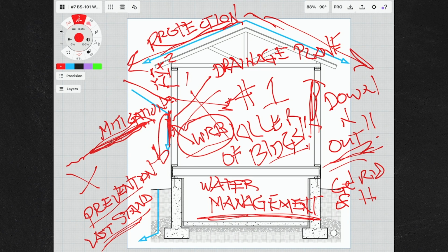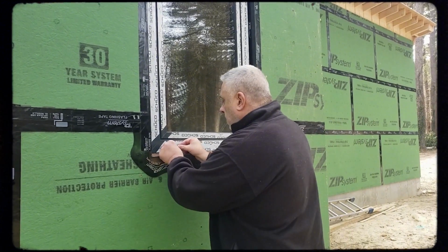Yep. Right. And most of the time, the good window companies are taking care of that. They're not selling you a leaky window, right? They're providing you that protection. But all of the good window manufacturers also have mitigative solutions in their windows, their components. If water gets in, they have weep holes so the water gets out.